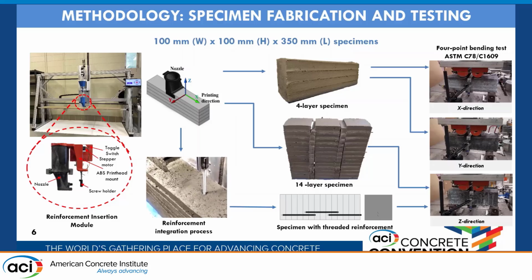And then finally, for the Z direction specimen, we've printed a 14-layer specimen at a maximum interlayer time gap of 3 minutes, and then tested in the Z direction.